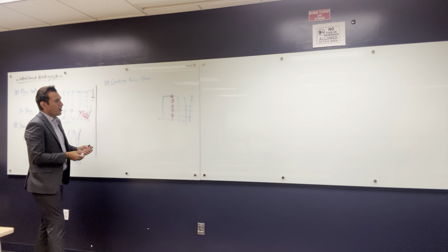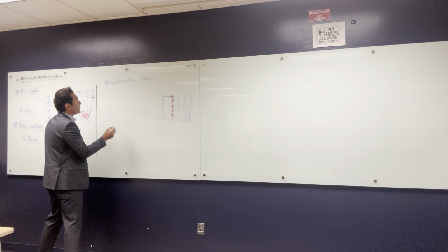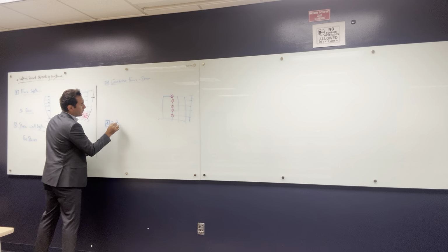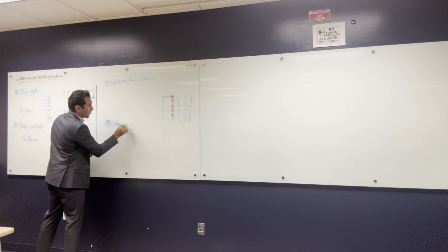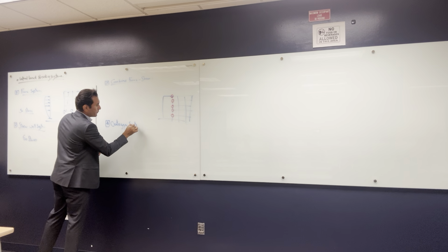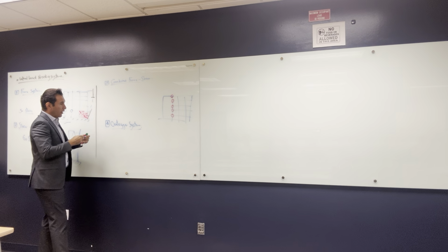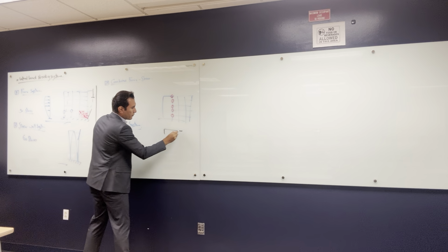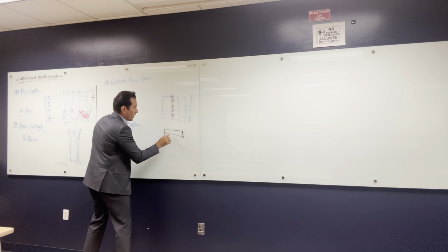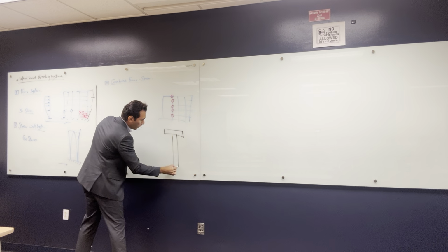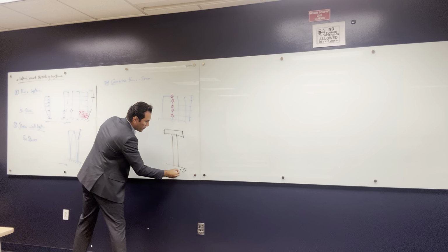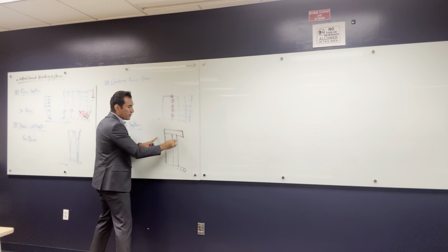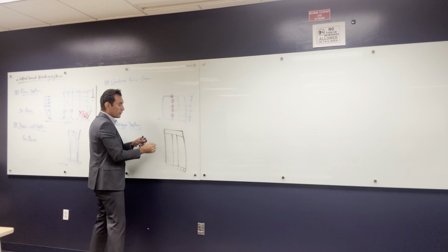And then we start talking about the outrigger system. So the outrigger system was something like this, and you have your shear wall like that, and there's the base, and we said we are gonna make a really deep beam and connect this beam with the column system in the building.